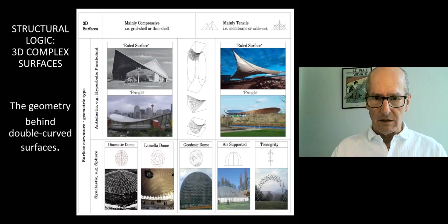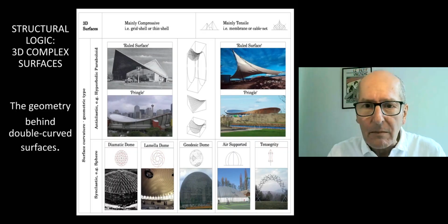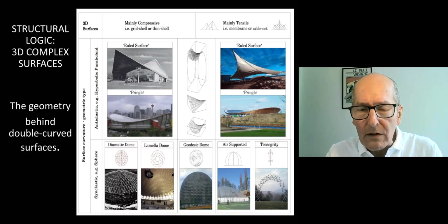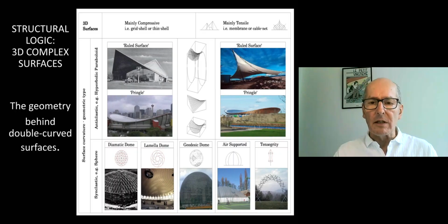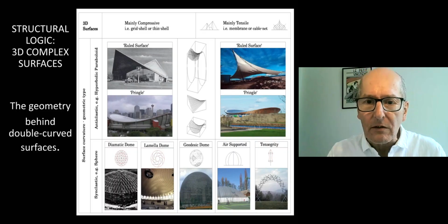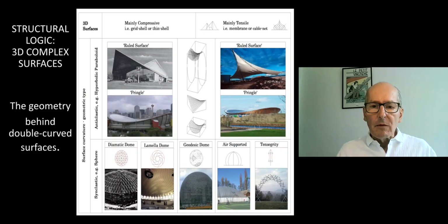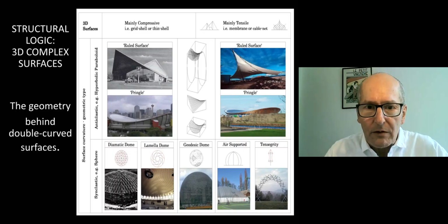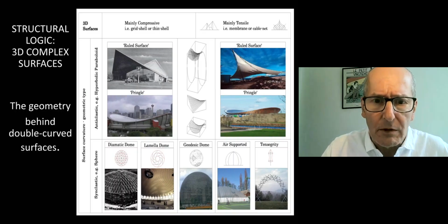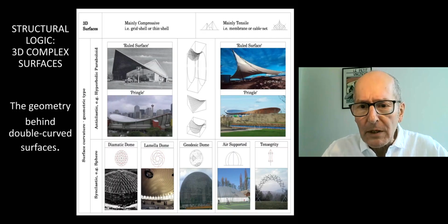And interestingly, if you look at the diagram now, you can see that they come from the central drawings, these are catenoids, and you connect the catenoids with one of those arched shapes, and then you start joining the dots, if you like, and you will quickly develop both of those types of surface. And these three-dimensionally are very efficient. You can use any arch shape to join the circles in the catenoid. Interestingly, they can work in pure compression and they can work in pure tension. So the top two images on the left are compressive shell structures, thin shell reinforced concrete, and the ones on the right are fabric. Well, the top one is fabric.